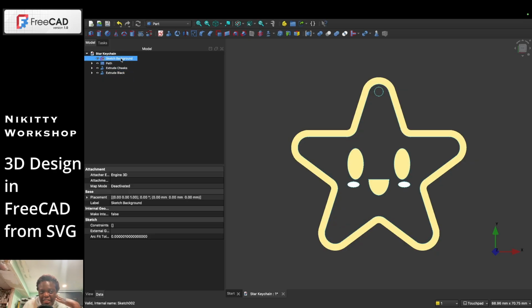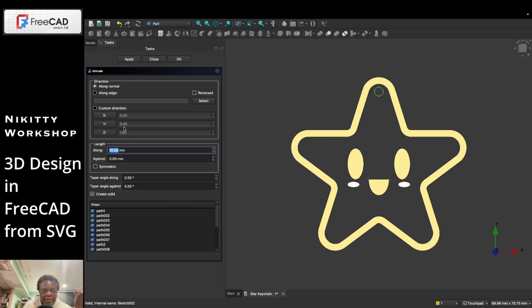So we're going to select the sketch. We're going to hit extrude. Same thing as before. Check, make sure that's a +1. We're going to put 2 millimeters because we want them all to be the same level. This is where too, if you're doing a single-sided one and you want the background to recess, but you want the outline and the eyes to pop out, you can adjust the height of the extrusion in that case. But I'm wanting it all to be one flat level because this is going to be a double-sided keychain. So we're going to do 2 millimeters. That's positive. We don't need to mess with reverse. And then we're just going to click OK.